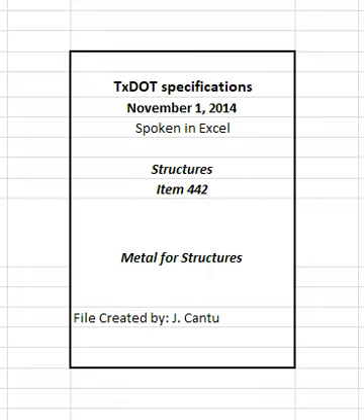2.1.3.5 Rail posts. Provide material for rail posts that meets ASTM A36 or ASTM A709 grade 36 unless otherwise shown on the plans. 2.2 Steel forgings. Provide steel forgings for pins, rollers, trunnions, or other forged parts that meet ASTM A668, Class C, D, F, or G, as shown on the plans.